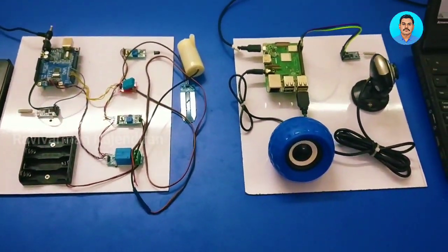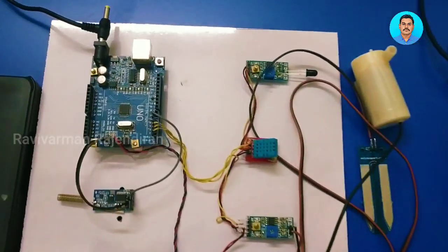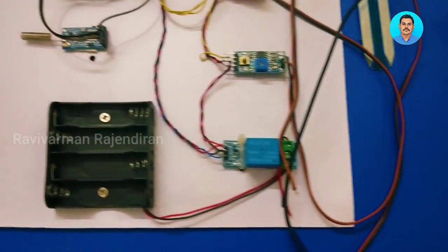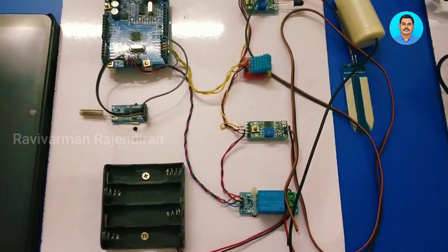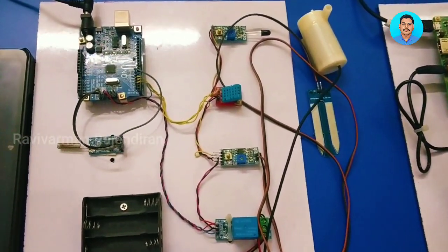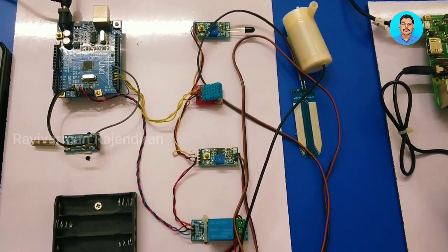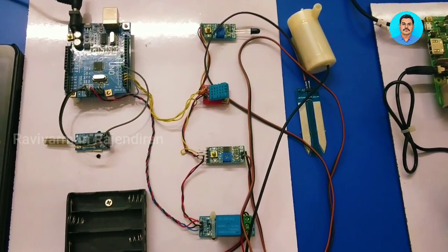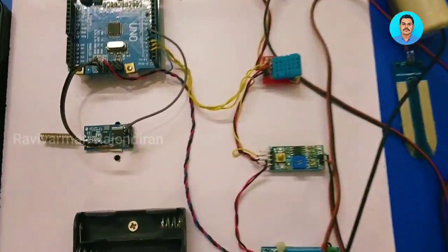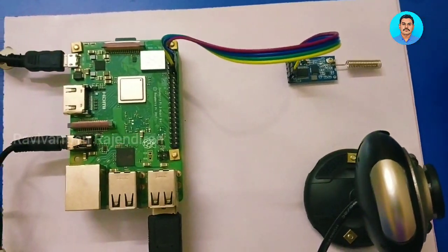The total system consists of a Raspberry Pi board, camera, speaker, RF transceivers, Arduino, fire sensor, temperature and humidity sensor, soil moisture sensor, relay, power for the pump, and its power adapters. So this is the entire system. It includes an Arduino Uno, which will capture the data from the fire sensor, temperature humidity sensor, and soil moisture sensor, and also control the pump automatically. All this data will be collectively formed as a data packet and sent via the wireless transceiver. This data will be received by another transceiver and given to the Raspberry Pi board.